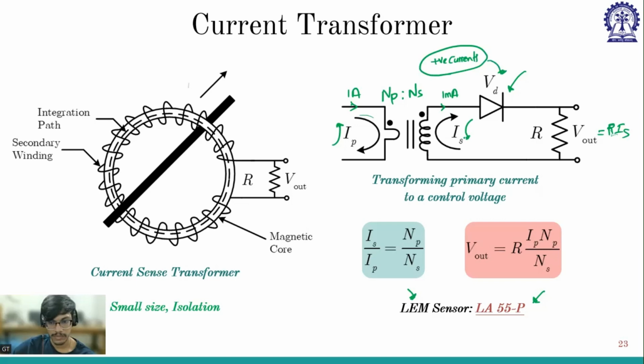So yeah, then this can be used for synchronous buck. Like if you are sure, in synchronous buck, current is going less than 0. But if you are sure that current is always positive, then you can use this. I'm coming to that example, where this can be used. If current is going negative, then it cannot sense.